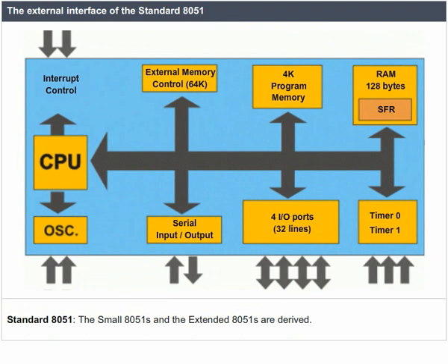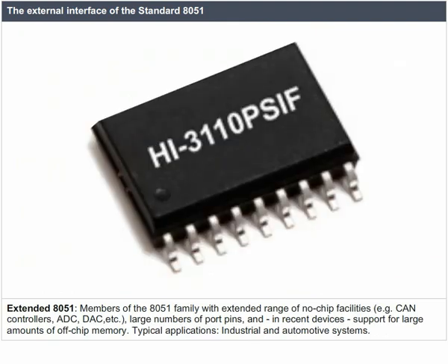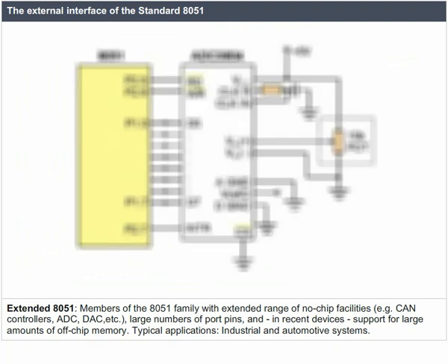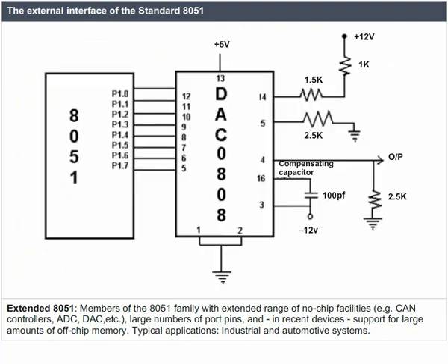Standard 8051. The small 8051s and the extended 8051s are derived from it. Extended 8051. Members of the 8051 family with extended range of on-chip facilities, for example, CAN controllers, ADC, DAC, etc. Large number of port pins, and in recent devices, support for large amounts of off-chip memory. Typical applications: industrial and automotive systems.